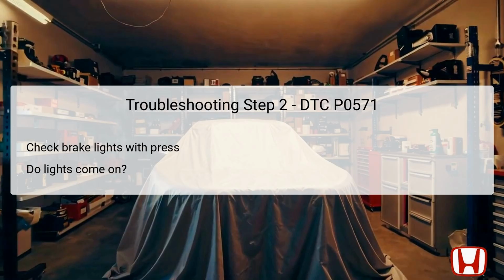However, if the brake lights do not come on, this points toward a problem with the switch itself or its connection to the vehicle's electrical system. Conducting these light checks provides crucial information needed for pinpointing the malfunction within the circuit. It's an essential part of the testing process to ensure reliable diagnostics for the P0571 fault code.